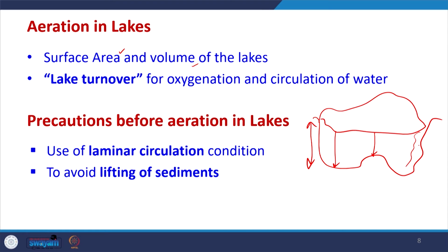These things have to be analyzed beforehand, before installing these aeration units at a certain depth, so that the plume rises and there is proper mixing. So, this is a possibility. When the plume rises, it will cover this much area. So, we will install the aeration units in such a manner that the whole of the lake gets covered, and mixing is also proper all throughout the lake.